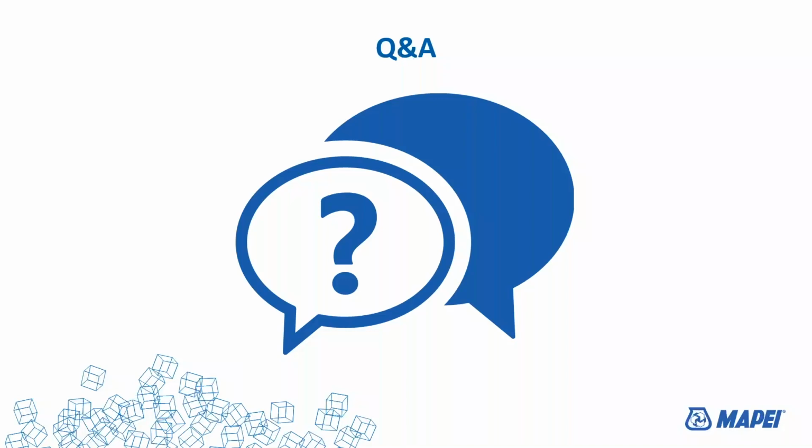Gotcha. Okay, after how many days of applying grout can we apply the sealer? And they're asking specifically about a silane siloxane sealer. Okay, silane siloxanes are quite good. They both have benefit. Each company is going to be a little bit different. In MAPEI's grouts, I think on the porous grouts that they're talking about, I believe they say wait 48 hours before applying anything like a sealer to it. Maybe as much as 72.